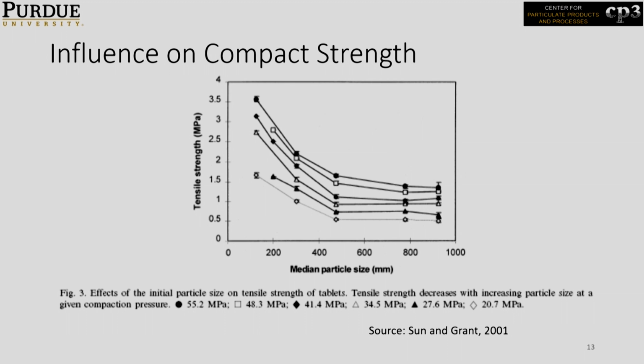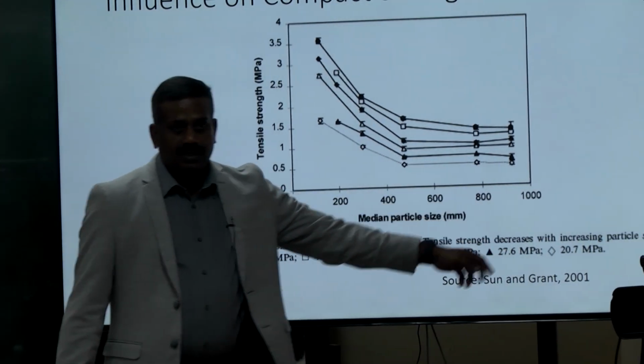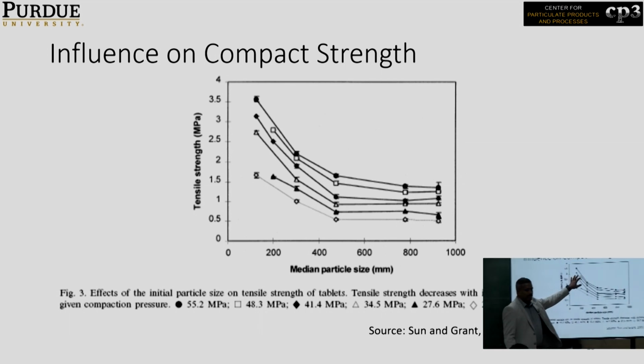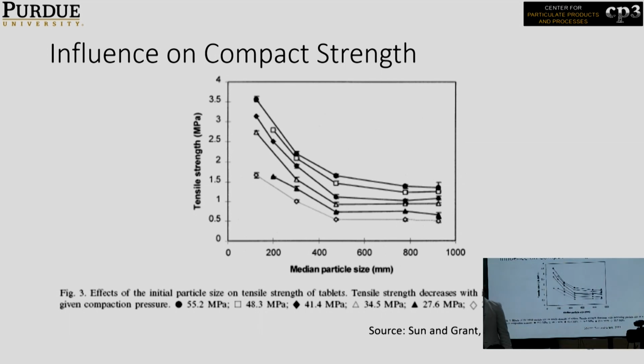So compact strength, again, we will talk about tensile strength, etc. But with the increase in particle size, the compact strength goes down. So if you are making any food powder tablets, like nowadays there has been lots of work going on making dairy powder compacts, well mixed dairy powder compacts so that they dissolve quickly. If you are going to work in that industry in the future, make sure your particle sizes are small so that they will have good compact strength, so that they won't break during the handling process. Okay.